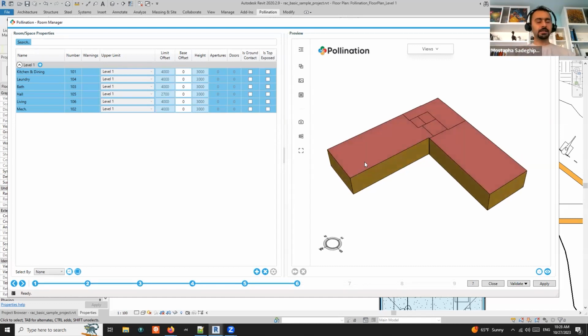So this thing that we added, the column here, it fixed our problem. But if you do this with a model that other people are also using, you're now close to getting fired by your BIM manager. Why? You just changed something that you might not have had the right to change. If other people are using this room to report something, or they have it in their views and everything, and you remove this column, you basically changed all that.